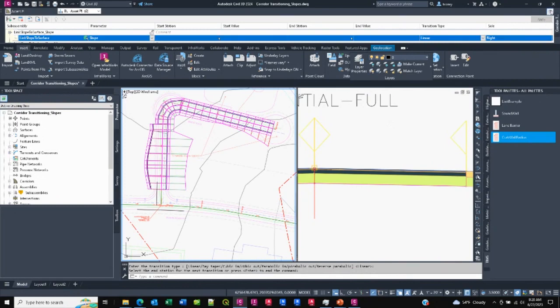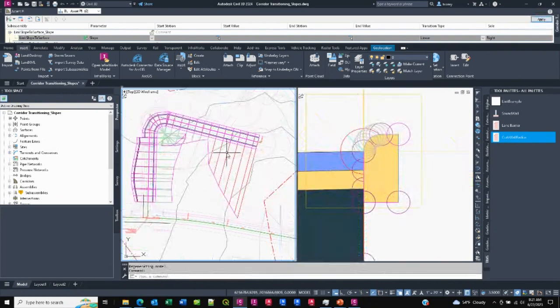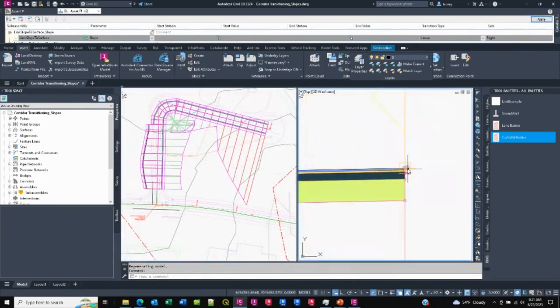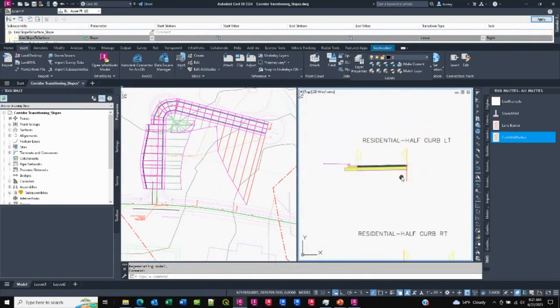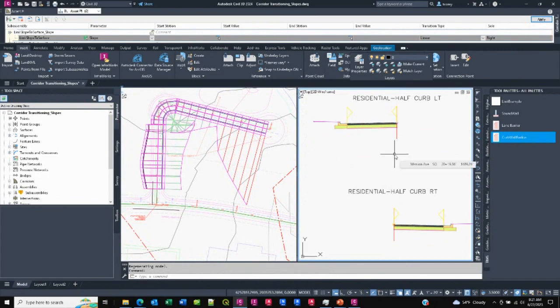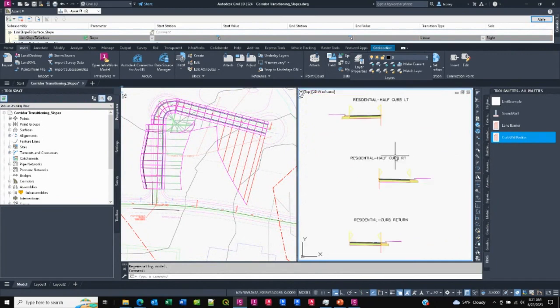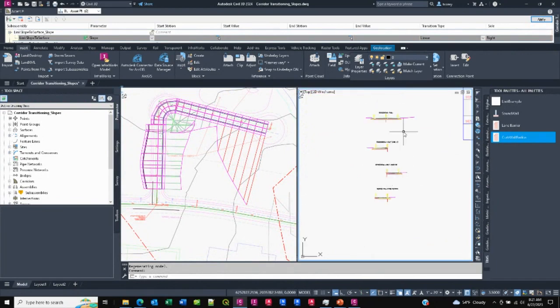All right, I want to show you width. So let's just do an undo back, act like I opened this up fresh. Undo, B for back. So the first thing I'm going to do is get rid of the daylighting on that. I just want to adjust the width of the lane, show you how you can do that. I'll just delete that and rebuild the corridor.